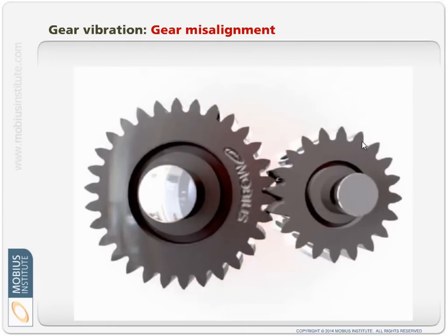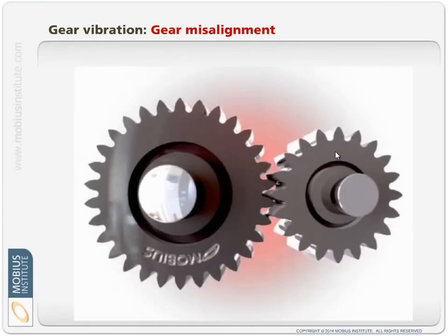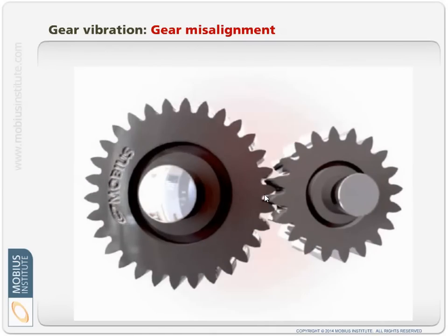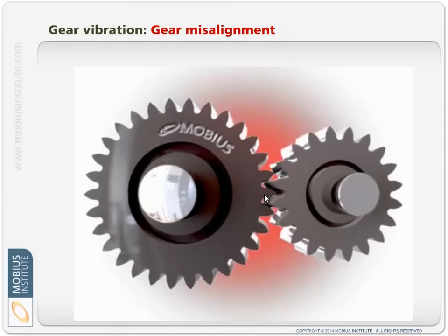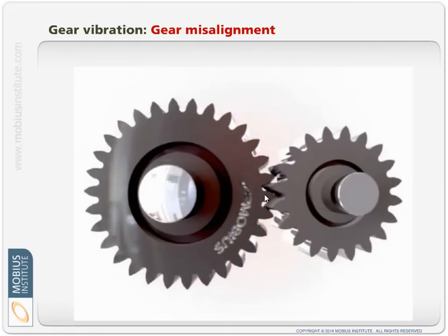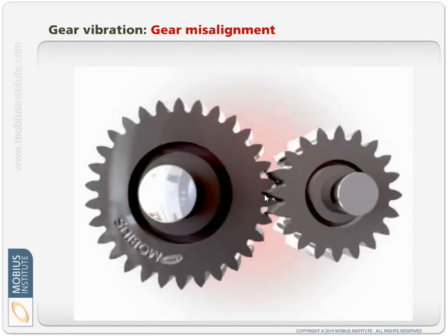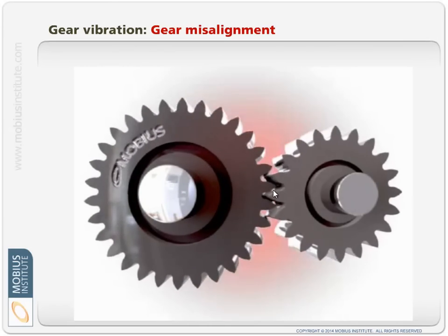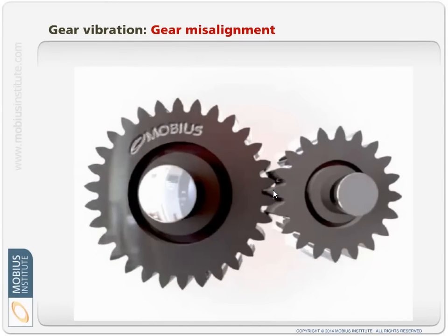In the case of misalignment, we've got one gear which is not aligned correctly to the other gear. It could be an assembly error, it could be that there's excessive wear in one of the bearings. There's various possible reasons, but if you look at this exaggerated animation, we're not really expecting there to be a lot of modulation in that vibration. The two gears are sort of at a fixed relative position, assuming that that is the case, and therefore our Gearmesh force will have changed because of the misalignment, but it's sort of constant per rotation.